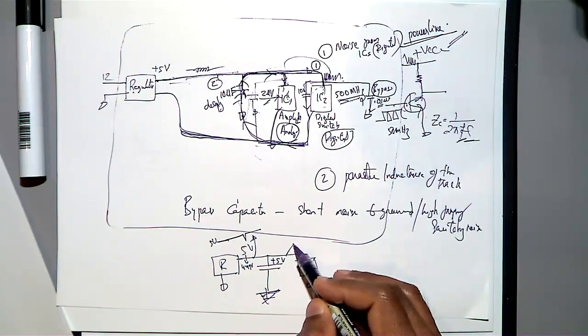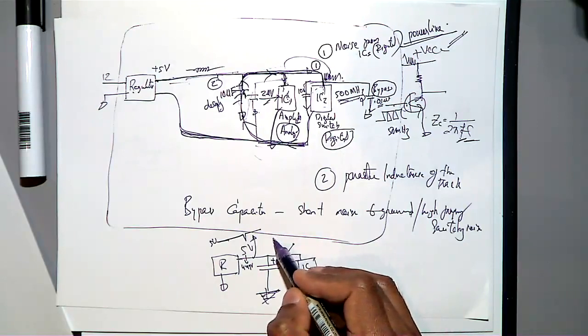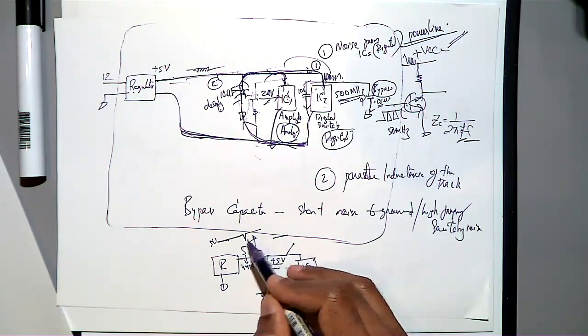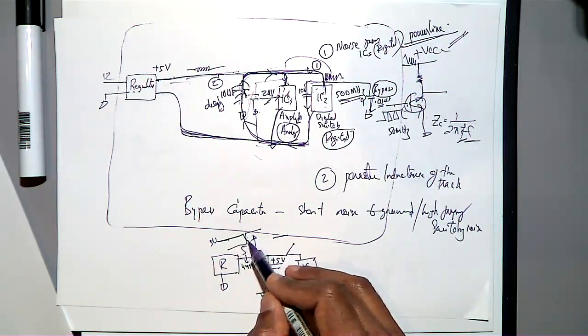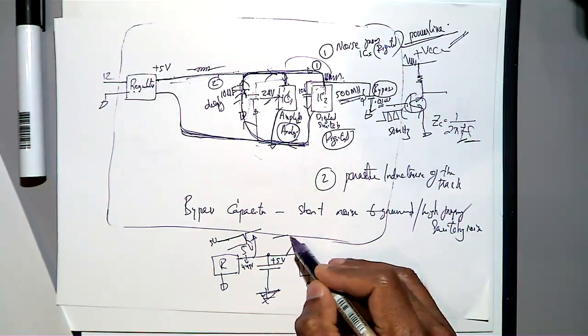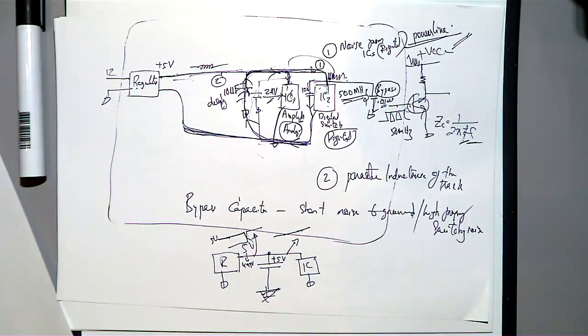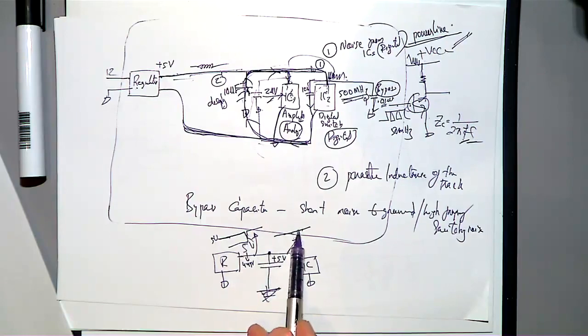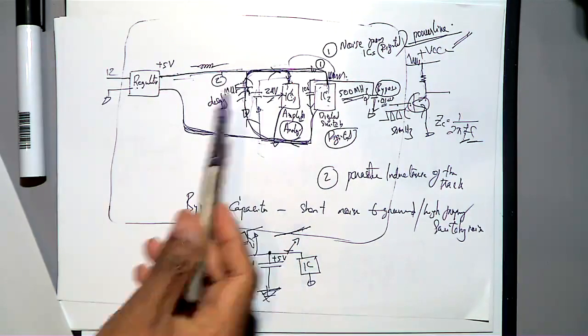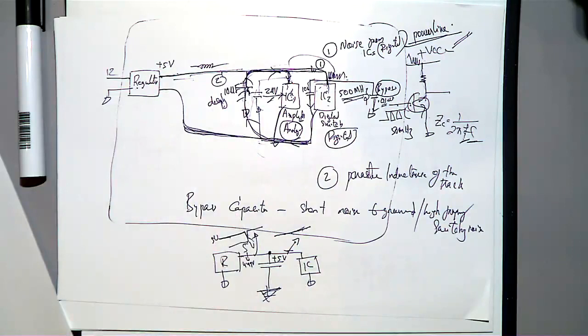Here you will not get that spike. Why? Because the spike will come, but the capacitor doesn't like change in the voltage. So when this part comes, the capacitor will discharge that part at this point, so that here you will get a smooth line. If the capacitor is connected to something and the voltage is reducing, the capacitor will discharge and compensate for it. So for a spike also, the capacitor will compensate that spike and you get a straight line. So that also is good. That decoupling can even smoothen your power supply.